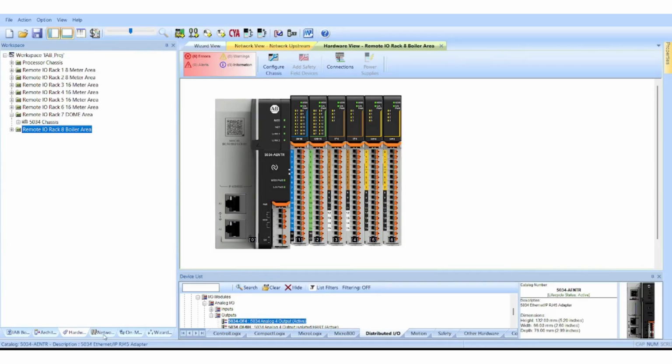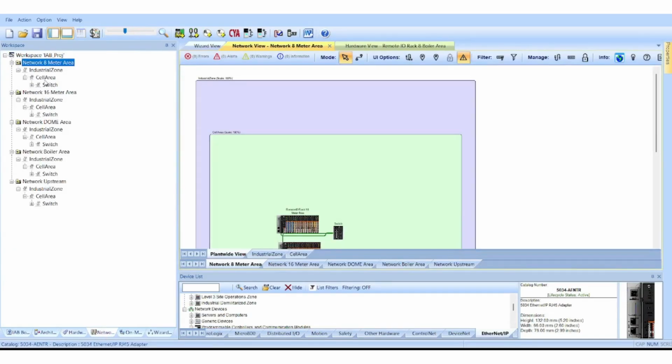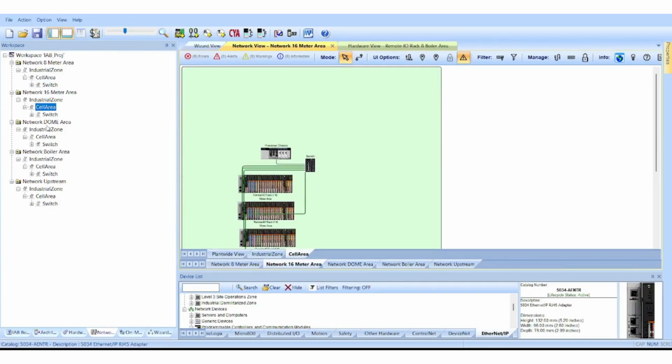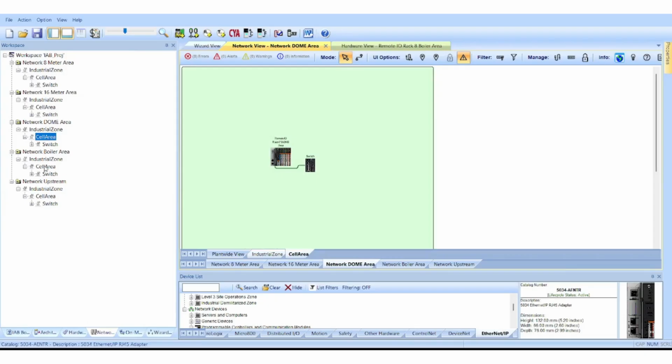Once the architecture has been configured, Integrated Architecture Builder can help us prepare the hardware bill of materials. This is one of the major benefits of developing the architecture properly inside IAB. Instead of manually creating a list of part numbers, we are generating the BOM from an engineered system configuration.